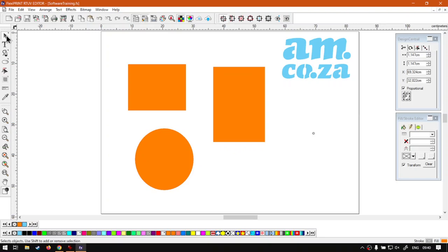Now when it comes to snapping, there are 2 main operators. Either we can move and snap, or we can adjust the scale and snap. When it comes to moving, if you click this thing and hold the left mouse button in, you'll see our mouse cursor is at a certain location. Wherever we started our click from, that's where it's going to snap it to.